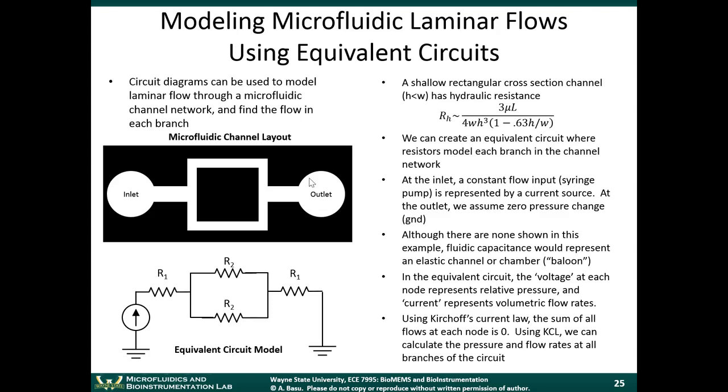So let's say this is what our microfluidic channel layout looks like. We actually design our channels in a CAD program. We would draw the dimensions of what the channel will look like. This is what it looks like from the top view, so this is the width and the length of the channel. We can build a network that looks like this. This is the inlet, and this is the outlet. The idea is that we'll attach our source, probably some sort of pump, to the inlet. We'll let the fluid flow through this network, and the outlet will be connected to some sort of waste container.